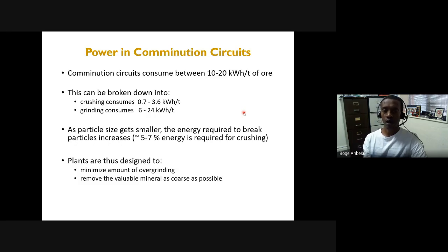That's one way of avoiding over grinding. And also, whatever you recycle back into the mill needs to be of controlled size. Some places are actually trying to minimize the grinding by trying to do both crushing and grinding at the same time. So instead of, for example, using a compression force, they're trying to use something that incorporates both the crushing and grinding in one equipment.